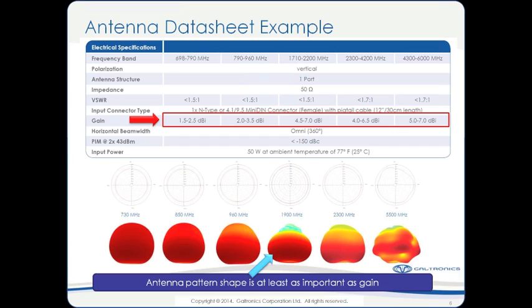That's because the two messages are correlated, and when they're correlated, I'm not actually able to separate the information well. Now, when I have decorrelation between the signals, I'm more able to separate those signals, and the way that you get decorrelation is through the introduction of multipath.